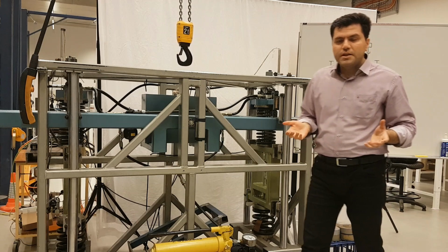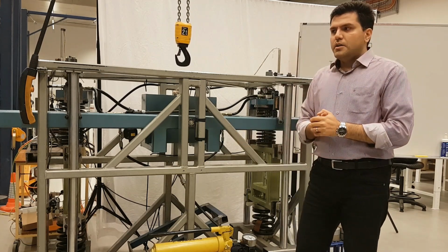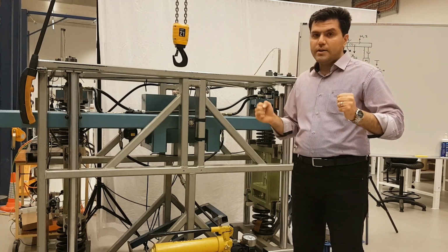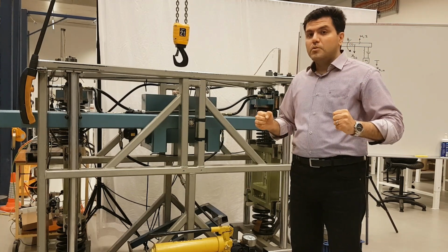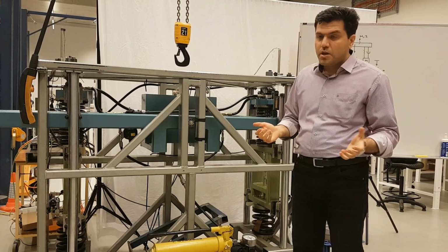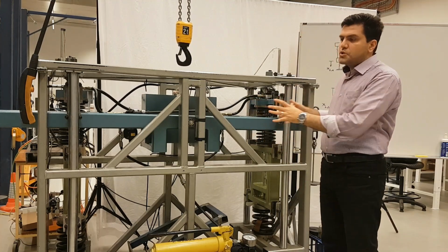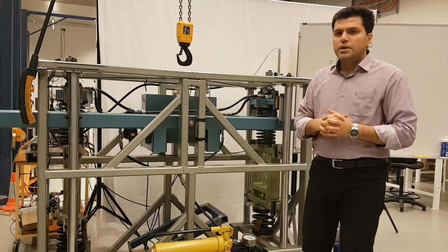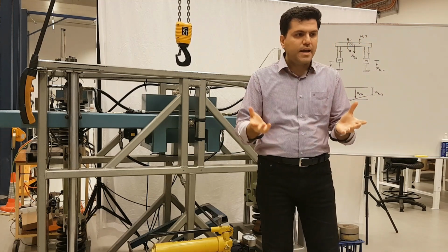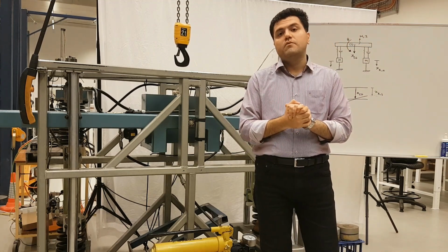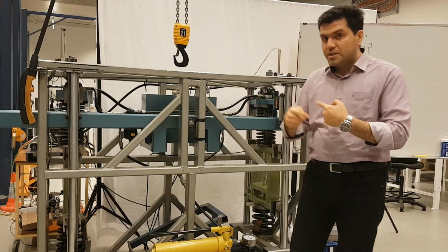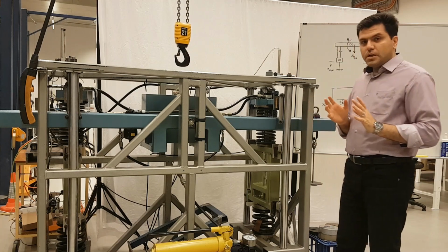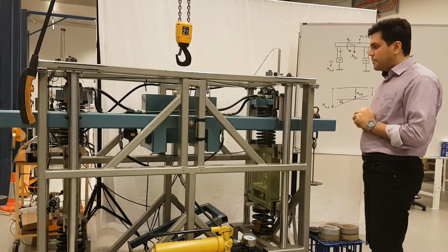And also in a vehicle, in most of the cases, it's very hard to excite only roll mode without exciting bounce mode. And so here we do have such scenarios, bounce and roll mode together. But the point is that if you are going to extract the damping ratios of roll mode only, then you need to do some signal processing and some mathematical calculations. I will show you what types of calculation you need to apply.